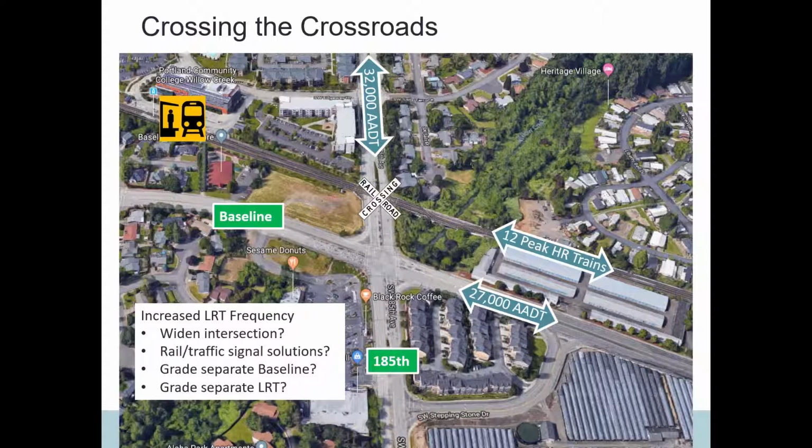So that sets the stage of our area. Oh, and one other unique aspect is when this was all constructed, the eastbound left was removed, and that traffic is accommodated through a jug handle movement here, just to minimize the conflicting movements and increase as much green time southbound as we can get.